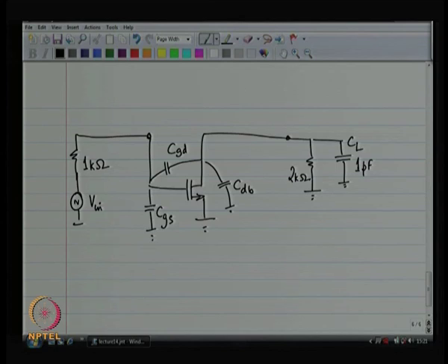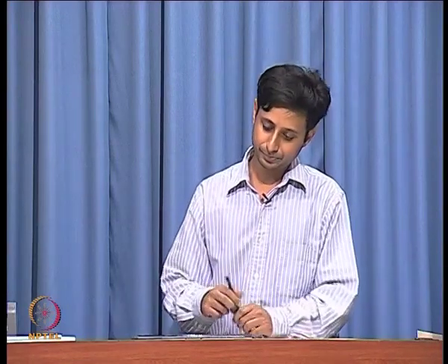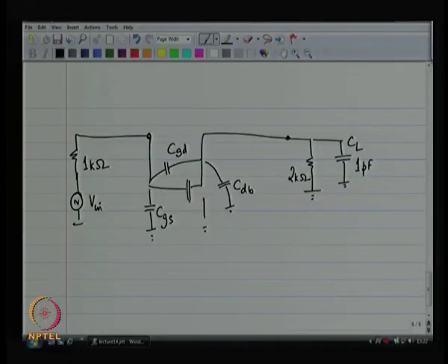And the MOSFET, in addition, we have GM, we have got RDS, and GMB is between body which is grounded and source which is grounded. So, the current going through GMB is going to be 0. So, you can safely ignore that. Let this be over here.